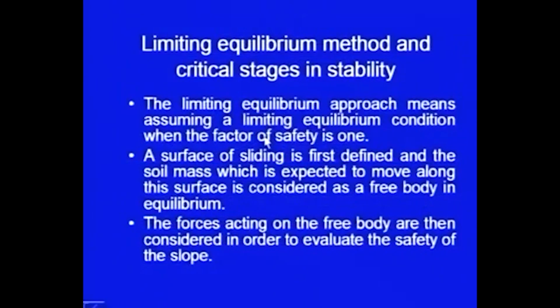Now, before we start the actual analysis, let me discuss some more points, some philosophical points. First of all, I am taking the limiting equilibrium method and critical stages in stability. Some discussions I would like to have on these, though some of these points we have already discussed. The limiting equilibrium approach means assuming a limiting equilibrium condition when the factor of safety is 1. This I have been emphasizing right from the beginning.